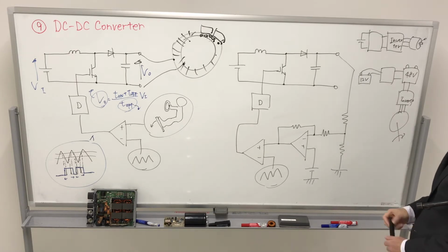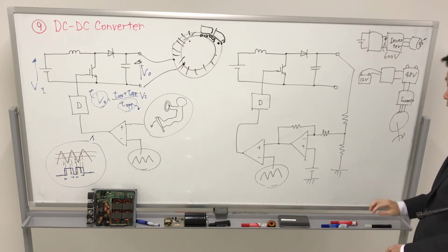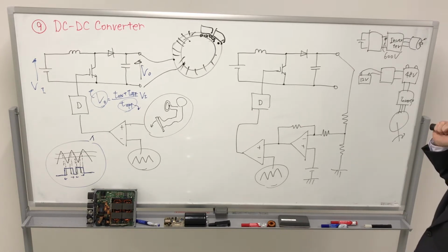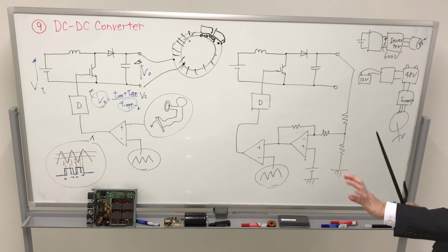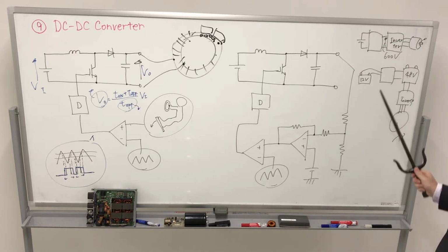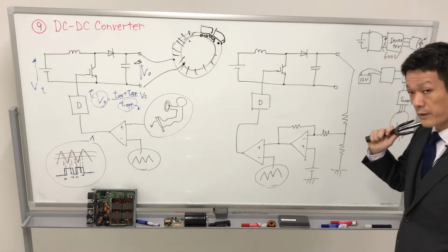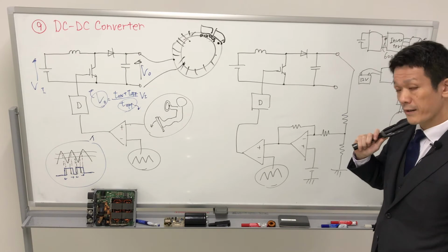However, in the case of the Prius, the voltage is 600 volts. In the case of the European mild hybrid electric system, the main driving is by the engine, so 48 volt is for torque assist, around 10 to 12 kilowatts. Audi's is 22 kilowatts maximum motor power. However, the higher voltage type obtains higher power, around 50 to over 100 kilowatts.